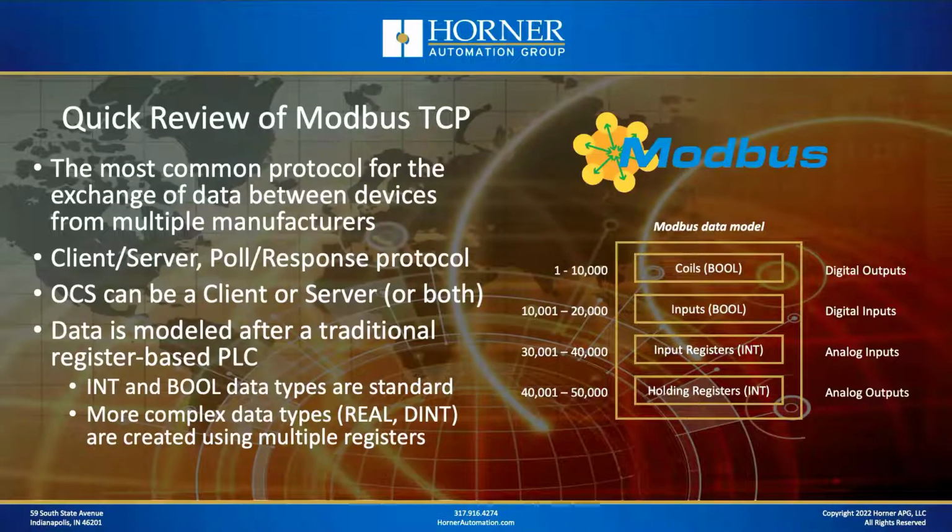All right, here's our quick review of Modbus TCP. Well, as most of you know, it's the most common industrial protocol for the exchange of data between devices from multiple manufacturers. It's a client-server poll response protocol. That means typically you have a client which is polling a server or multiple servers and sending them queries, and they're getting responses back. Now, from an OCS standpoint, an OCS can be a Modbus TCP client, a Modbus TCP server, or both.